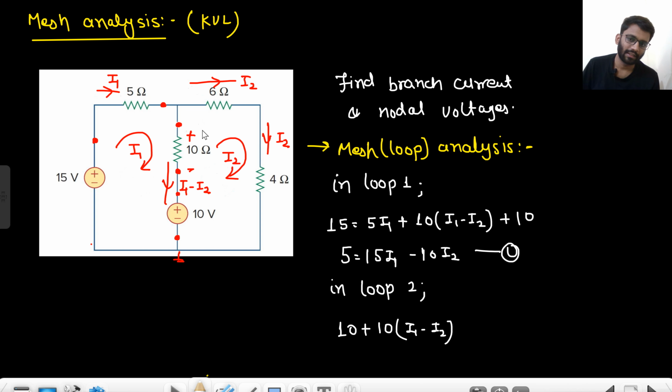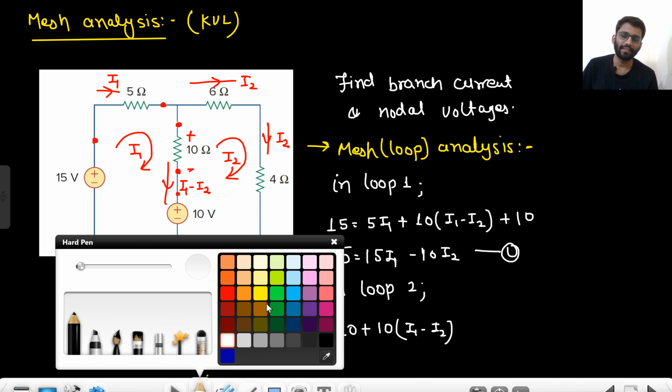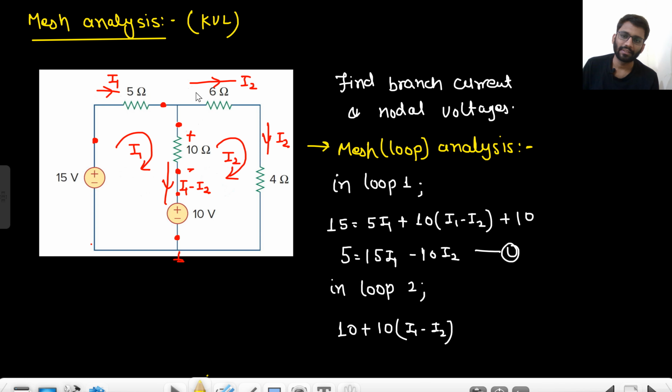Now we will work like this, right? Forget about your working direction for now. We need to see the direction of current first. The direction of current is like this, from here to here, so from here to here we will see negative. In this branch as well the current is like this, so from here to here we will also see negative. You first need to see the current. On the basis of the current, you make the voltage drop, plus and minus, and then you work. First you make the voltage drops and then you work.